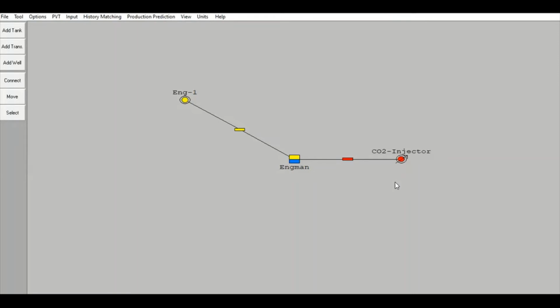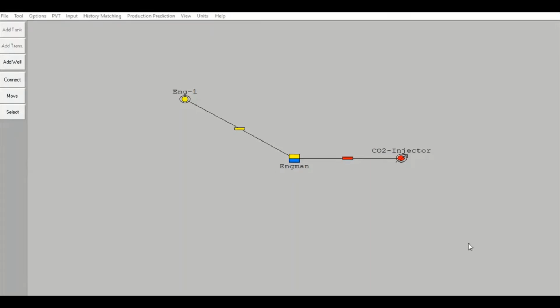Okay, we get the gas injection profile, we get the reservoir pressure profile, flowing bottom hole pressure profile, wellhead pressure profile, and then we can get the cumulative gas injected, which later on we can convert to mass of CO2 injected in the storage. So we will use the tank model to simulate our CO2 storage or CO2 injection. Okay, so previously we have learned about the characteristics we have in this model, in this simulation.